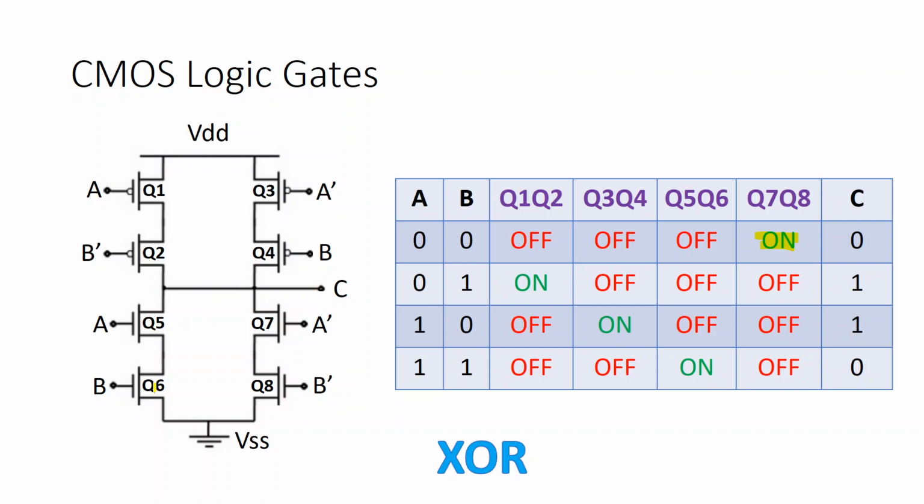But I should ensure Q5, Q6 channel is off, Q7, Q8 channel is off, and since A, B is 0, 1, you can easily read from this circuit that these channels will be off. Similarly, you can read for the other two combinations. You can look at the circuit and realize that these switch combinations are behaving in this off and on as written in this table.